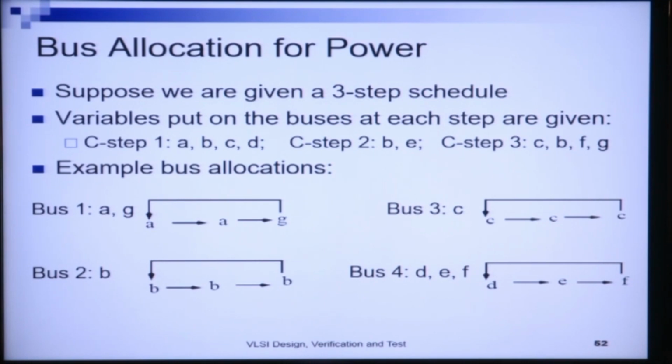So we can find an allocation such that the changes in variables on the bus lines are minimized. We will obtain a minimum cost allocation for a given set of bus lines, and this will provide a good allocation in terms of power as well. Thus, with this basic understanding of power aware synthesis, we come to the end of this module.